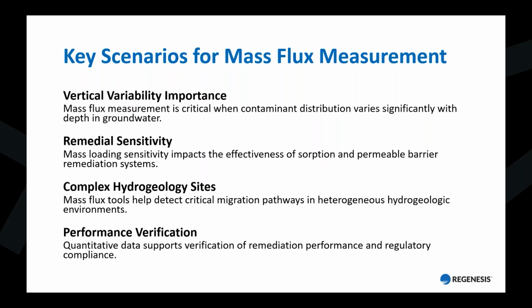And I think finally, the use of these flux tracers, or getting this type of flux information, is also really important if you're just trying to verify the performance of a remediation. It could be an in situ application, or it could even be natural attenuation. Having an understanding and measuring the flux coming through a system or off of your site, and how it changes over time, is going to help you assess the effectiveness of a particular remediation program or just what's happening naturally